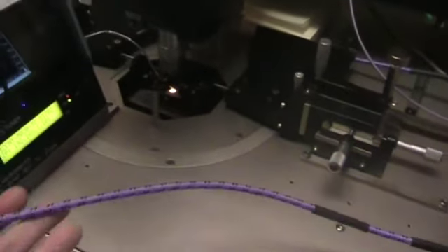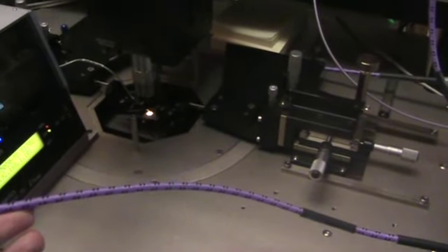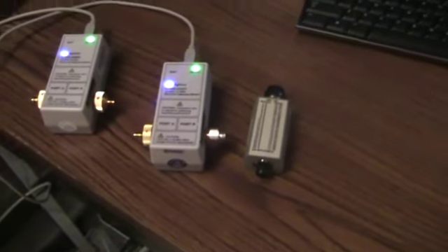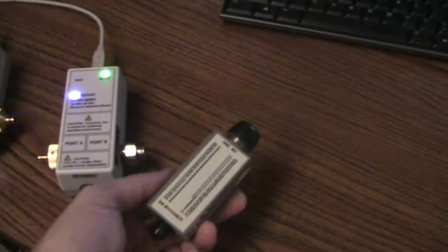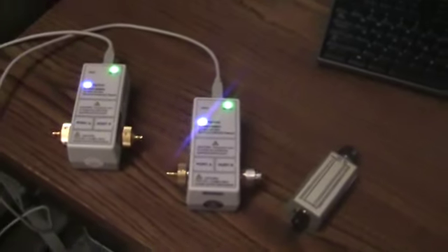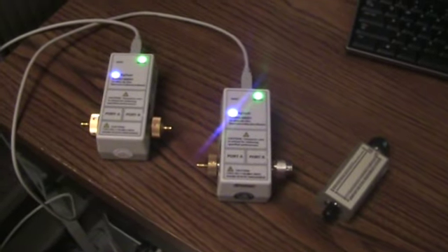In order to perform this measurement, we utilize Gore FaceFlex cables. These are the purple ones that are a little pricey, but well worth every penny. And then the calibration will be performed with Agilent equipment. We have a 15 dB ENR 50 gigahertz, this is the 346CK01 noise head, and then a pair of 50 gigahertz electronic calibration units from Agilent.